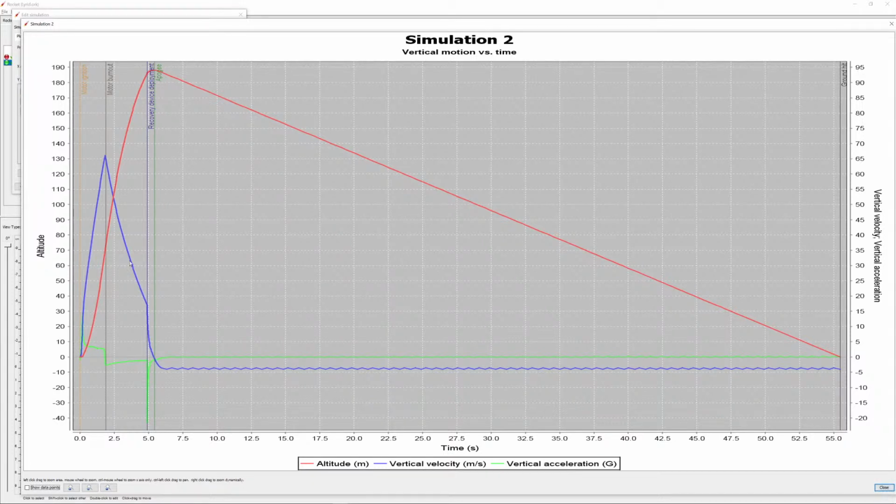So you can see that, and here's the exact problem: it ascended, and then the recovery device deployment, that's the parachute ejection charge, fired before apogee. Well, that's great, but the ejection charge is strong, but not too strong. It's not incredibly powerful stuff. So the recovery device deployed before apogee when it was still going up and the nose cone was still being pressed into the rocket. Well, the nose cone weighed quite a bit, so it didn't have the force to push it off.